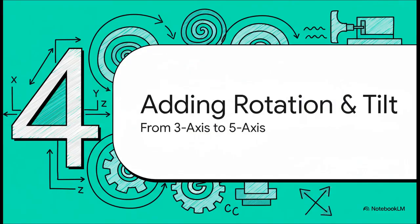So we've nailed down our linear movements with X, Y, and Z. But a three-axis mill can only come at the part from directly above. So what happens if you need to machine an undercut or some complex curving surface? Well, for that, we need to add rotation and tilt. And this is exactly why we level up to 5-axis control.